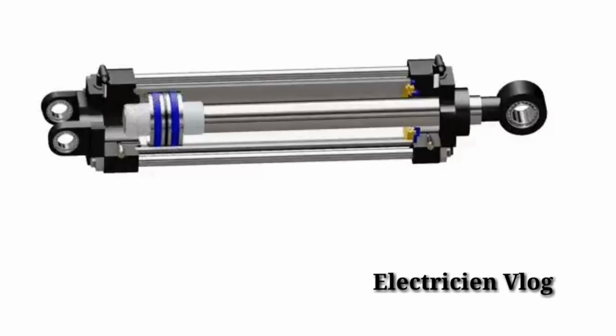Frictional losses on the interface of different surfaces also need to be considered while designing a pneumatic cylinder. The diameter of the rod and length of stroke are also determining factors for the capacity of the actuator.